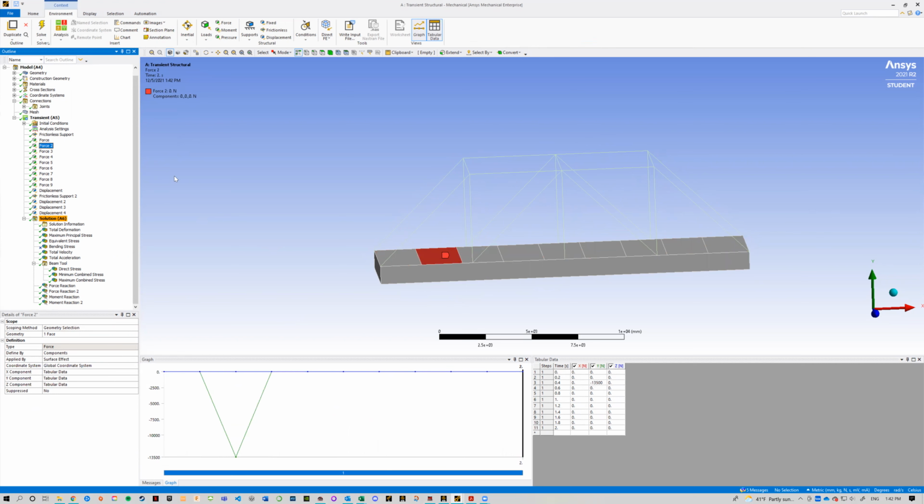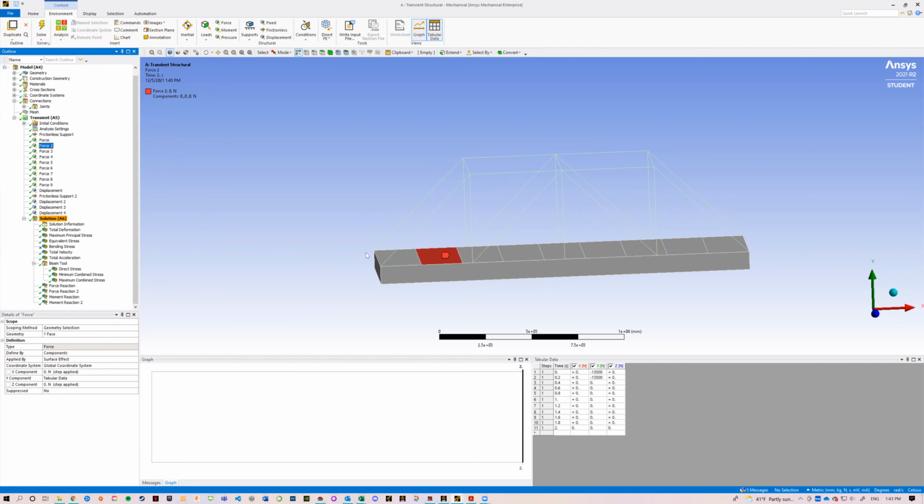It does take 2 seconds to get across the bridge, which is consistent with the 10 meters per second specification in the problem, because the bridge is 20 meters long. But it doesn't travel uniformly necessarily, because it's challenging to split the top face of the bridge into an even number of faces. It's much easier to do it in odd numbers of faces. So this is 9 faces as opposed to 10, which would have allowed me to vary it more consistently.